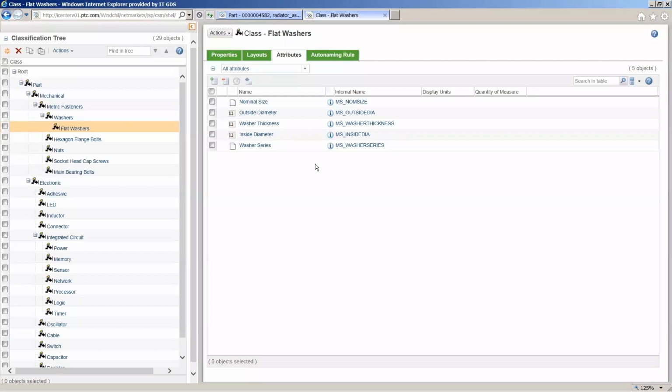Okay. So that's really Windchill parts classification in a nutshell. We went through searching for information using the classification explorer. We created a new part within a product and assigned it classes to search on in the system. And then lastly here, we took a brief look at the administrative side of parts classification, where you're actually able to come in, create and manage classification nodes and schema in Windchill.